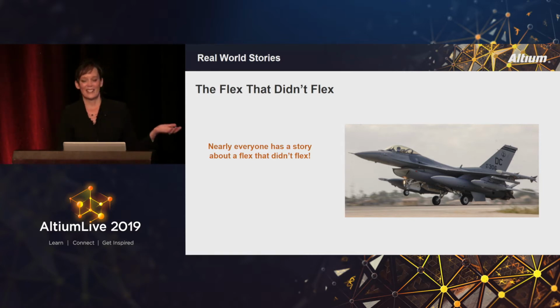This one is another example of mine. We had worked very diligently on the stack up for this. It was a 6-layer rigid flex. It had some crazy impedance requirements that we were trying to match. We ended up with some pretty thick copper, thick Kapton.